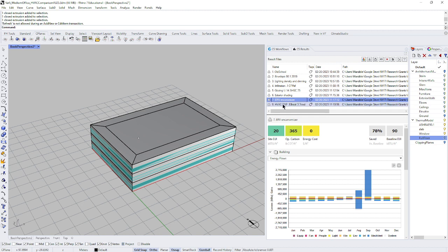Okay, anyway, so then the final thing I did was I looked at the HVAC equipment settings and I increased their efficiency. So I set the coefficient of performance of the heat pump higher, and I made the boiler a little bit better. And that also did a fair amount, right? If we'd been looking this whole time, we could see how these changed. So now we can see that mostly we're at mechanical ventilation and infiltration. In other words, this is heat we're losing through that ERV still, and this is heat we're losing, in one direction or the other, through air leakage.